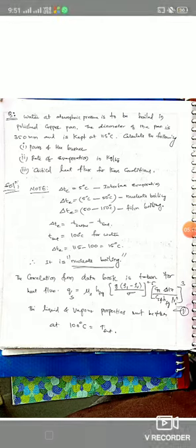Now there is a small note. According to the boiling regimes, on the x-axis it is excess temperature, on the y-axis it is heat flux. Depending on the excess temperature variations, the regimes are decided here. We know the three regimes: interface evaporation, nucleate boiling, film boiling. These three are distinguished with respect to water at 1 atmospheric pressure.